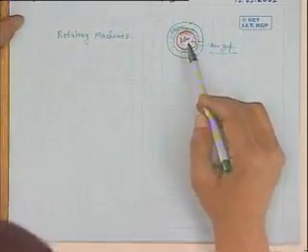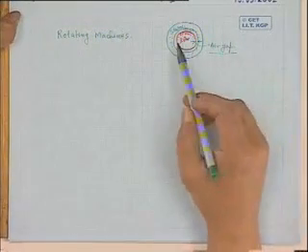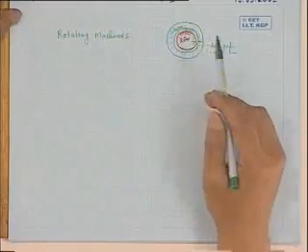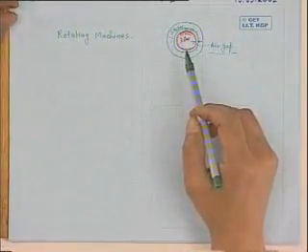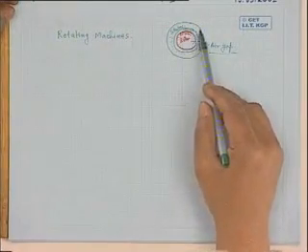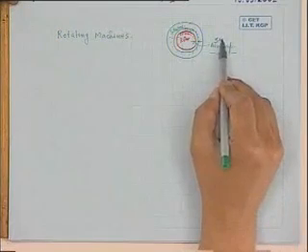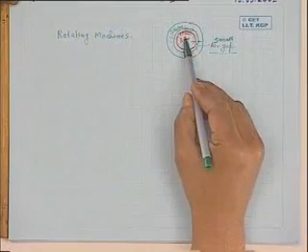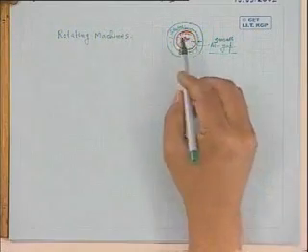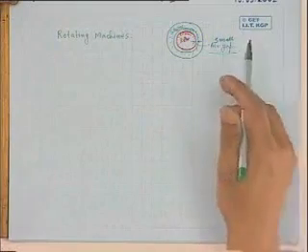Similarly, the rotor structure too will be made of iron and also slotted so that conductors may be placed in it, and that is called the rotor winding. And they will be separated by a small air gap length. And of course, in the central position of the rotor, there will be a shaft on which the machine will be rotating.